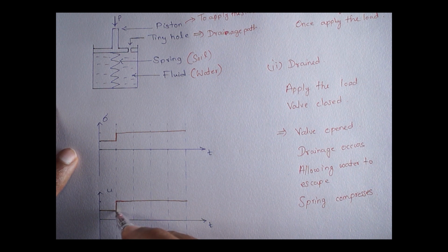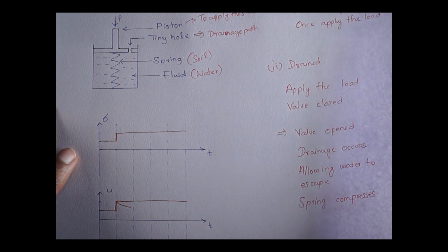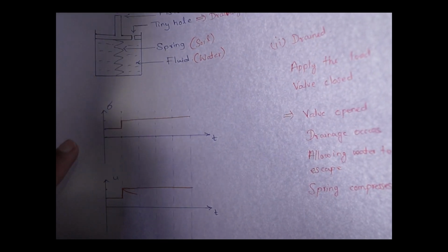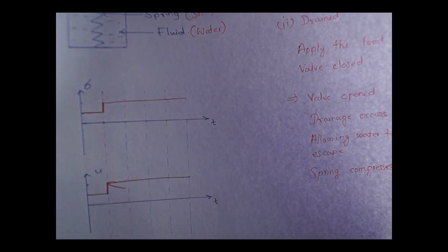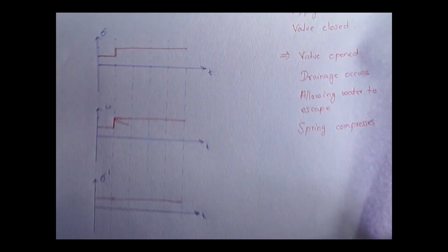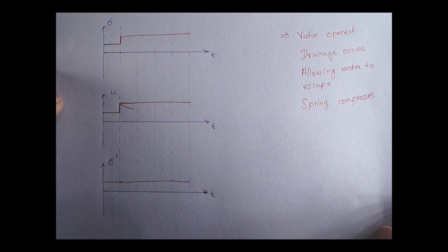It spikes up and then starts to decrease with time. Once the pore water pressure starts to decrease, the spring starts to compress, thus increasing the effective stress